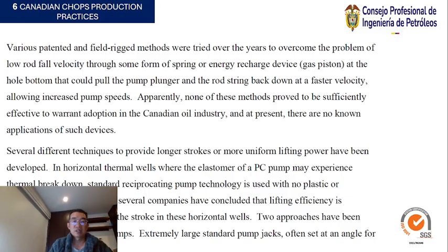Several different techniques to provide longer strokes or more uniform lifting power have been developed in horizontal thermal wells, where the elastomer of a PC pump may experience thermal breakdown. Standard reciprocating pump technology is used with no plastic or elastomeric parts.